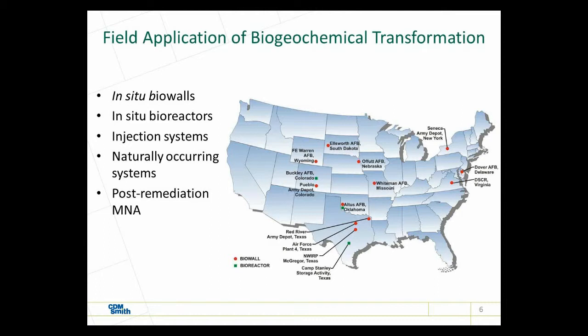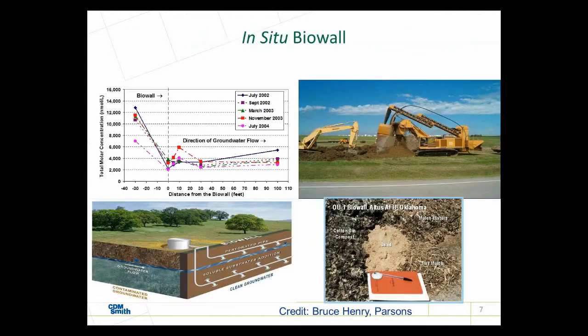But now we're thinking about it a little bit differently, is that it's not just the dead bugs that are promoting this process. It's also that the bioremediation process is reducing the natural minerals present in the subsurface, where in effect we're charging a battery, and that battery then can go ahead and continue to promote the reductive dechlorination process for years. We don't know how long, and it's going to be site-specific, but we are beginning to realize that that's an important process.